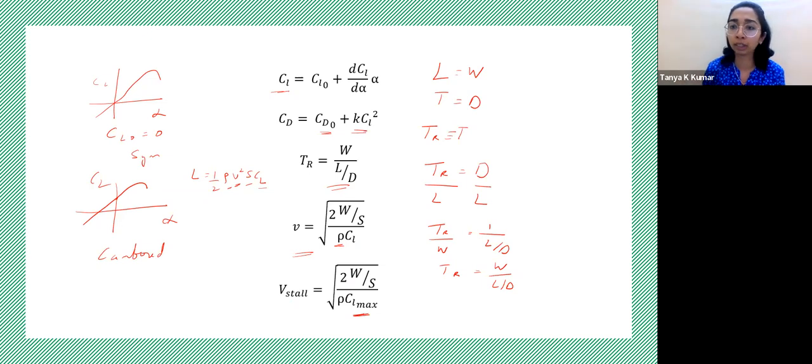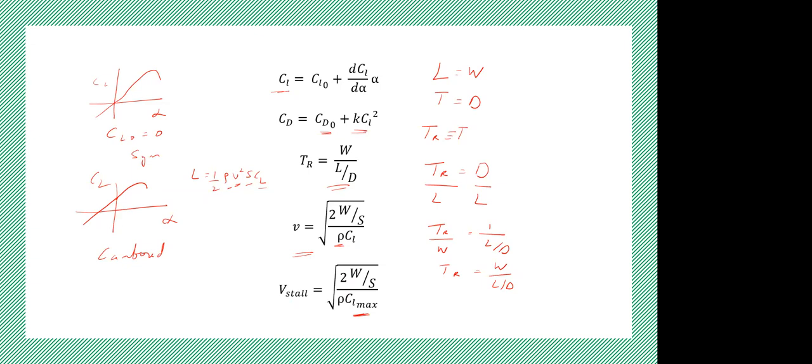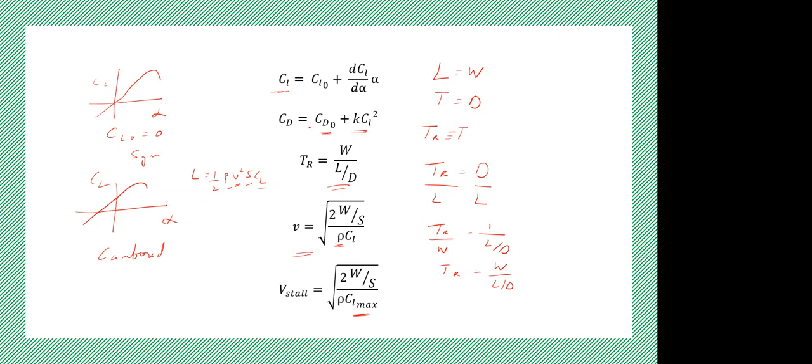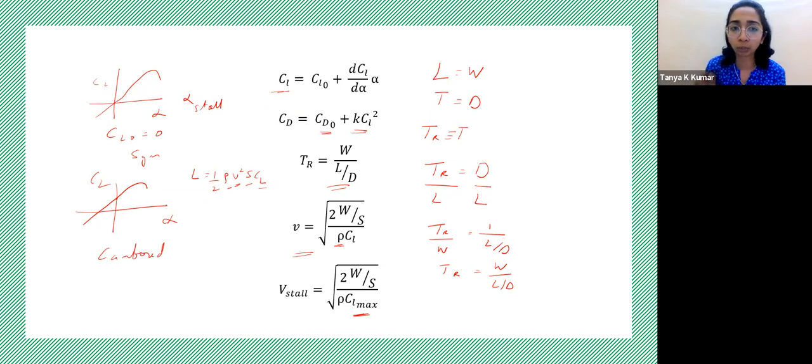Yes. What happens if you go below this speed? What if you try to fly your aircraft below that speed? The aircraft goes down. Yes. So it will cross the stall, the alpha stall, the angle of attack at which we saw the curve drop. Physically, if you take a cross section of the airfoil, at what point do you have this alpha stall? Why does this happen? You have an airfoil like this, and you have flow happening over it.